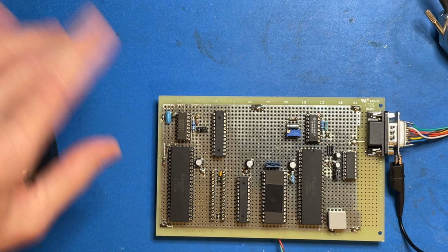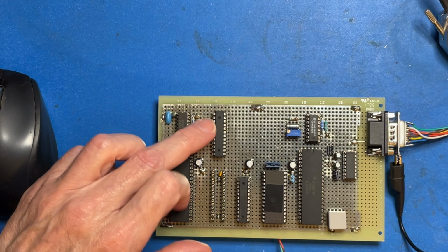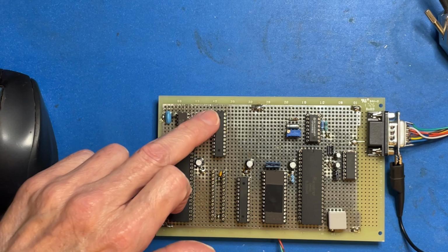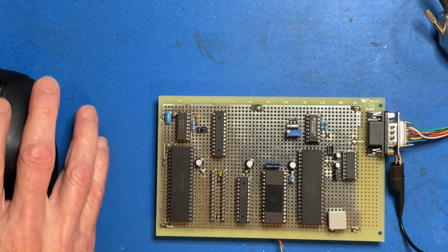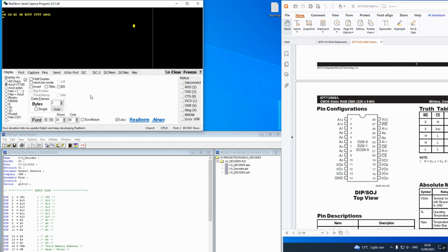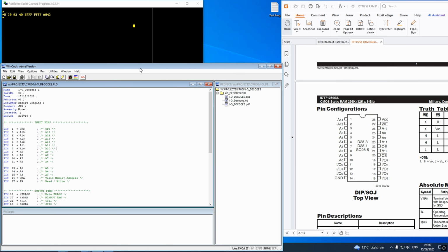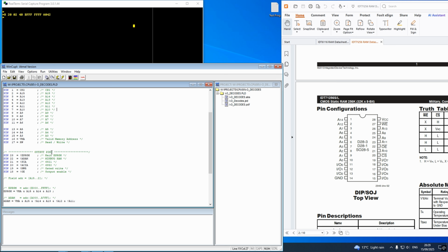I found out why it was completely dead after I tried that mod. I put a wire on the wrong pin. Put it on the right pin, it made no difference whatsoever. So I've done another mod now, which is reallocate the pin I was using for the main memory chip that are not fitted yet, which will take up the bottom 32K of the address space, because that's unused by the debug ROM and its memory and I/O,